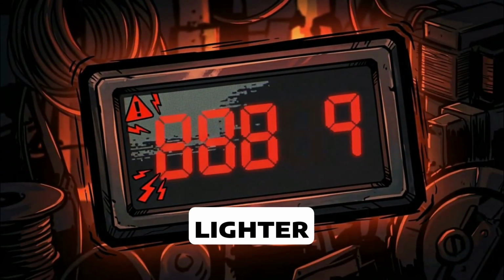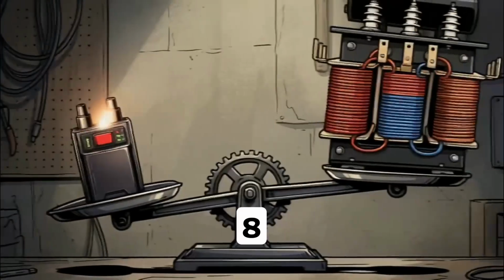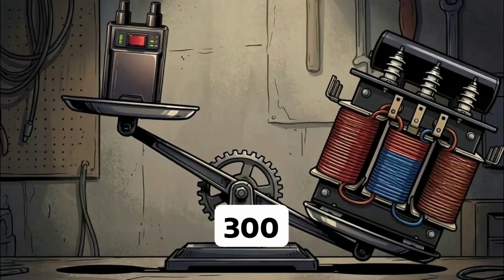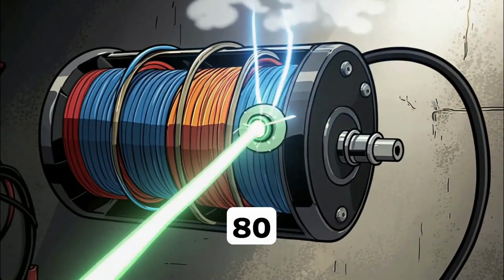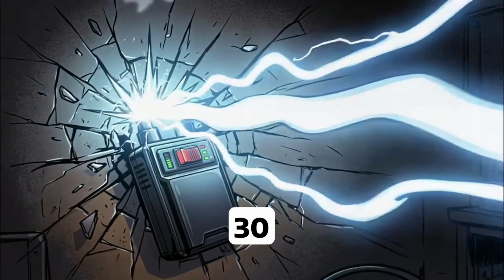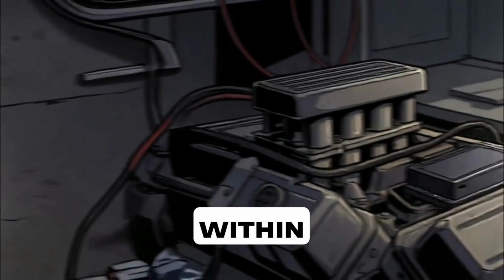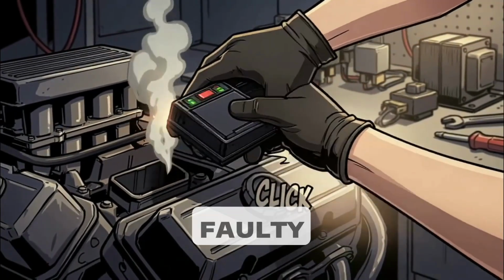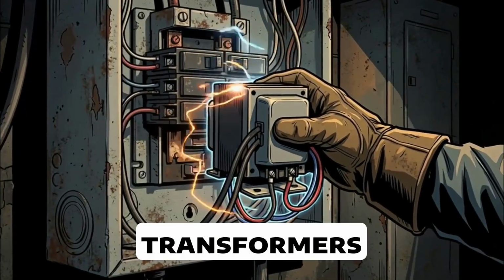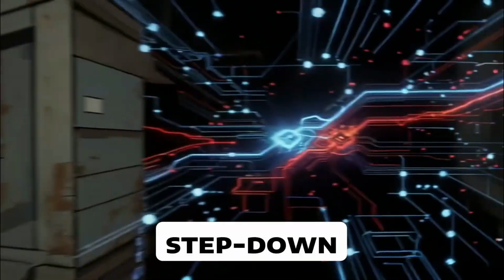Electronic igniters are lighter and more efficient than iron core transformers. About 1 pound versus 8 pounds, 45 watts versus 300 watts. They may work with 80 volts input and output 8,000 to 17,500 volts, with peaks near 30,000 volts DC. Check grounding, minimum 2,000 ohms to burner, and secondary readings within 20% of each other. Replace if faulty. Control transformers are usually 120 volts AC to 24 volts AC step-down units.